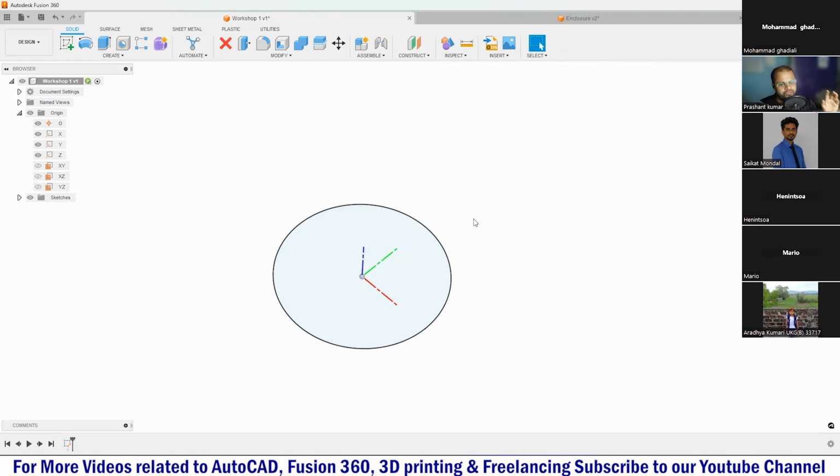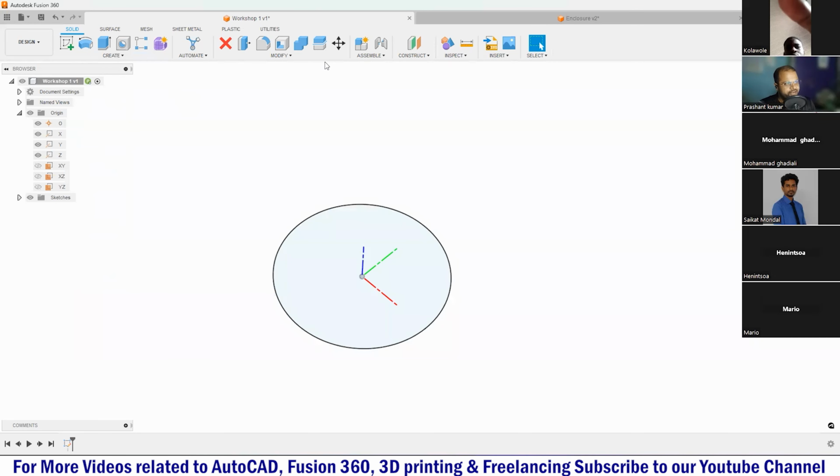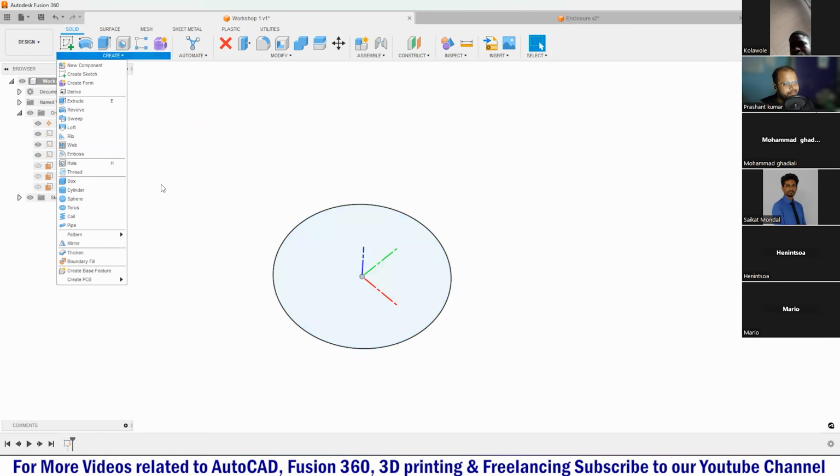Now, using this sketch, we have to convert it to a 3D model. So how can we do that? It's very simple. To convert any sketch to a 3D model, there is a tool called extrude that you will be able to find inside the create panel. So here are different panels, and this is how to identify where you can find your tools. See guys, anything you want to create, you will be able to find inside the create panel.